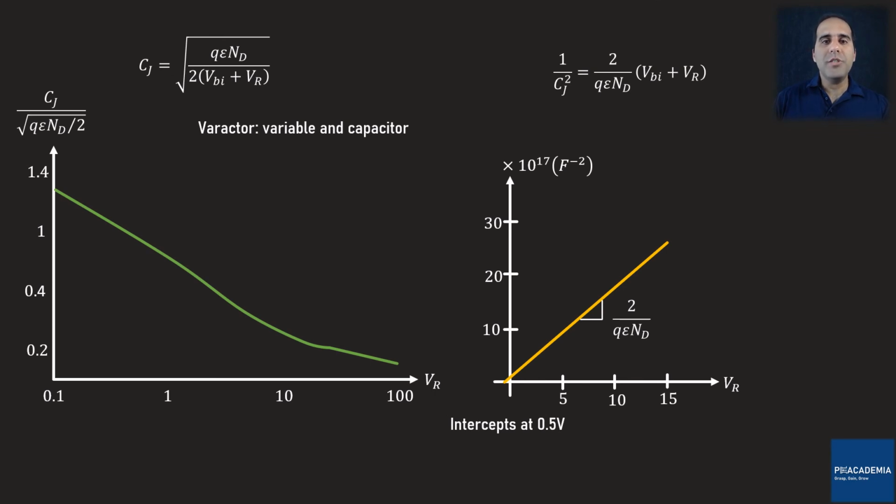What you could do is to look at the datasheet of the diode. In the datasheet, you should be able to see the junction capacitance versus the reverse voltage plot. Using this plot, you can simply calculate the donor concentration.